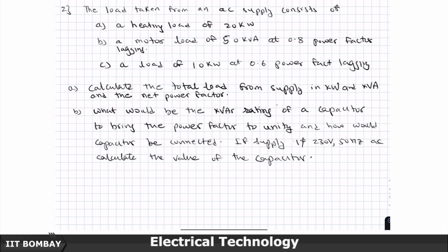We have already discussed this that we do not do series compensation. Series compensation is a different thing altogether. It is usually done when you want to alter the net impedance of a transmission line or a distribution line. That is not what we are trying to do. We connect the capacitor in shunt. So, it almost sees the same constant voltage. So, it gives you a constant kVAR compensation.